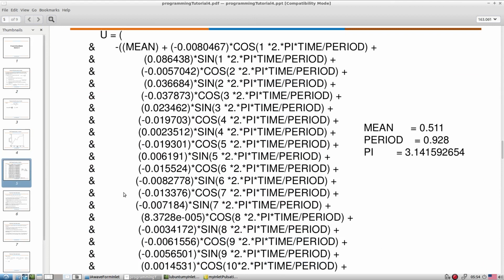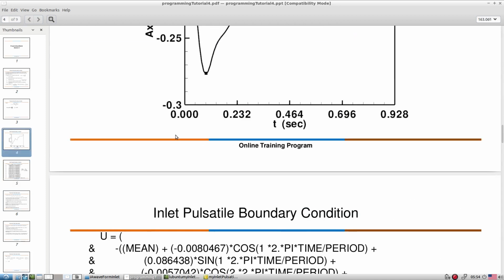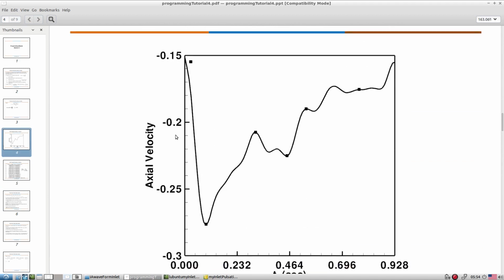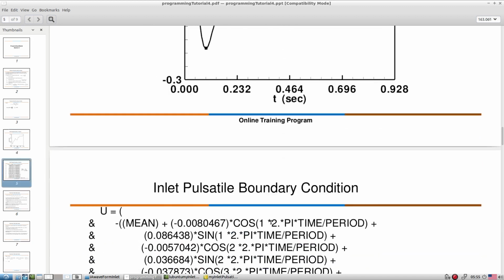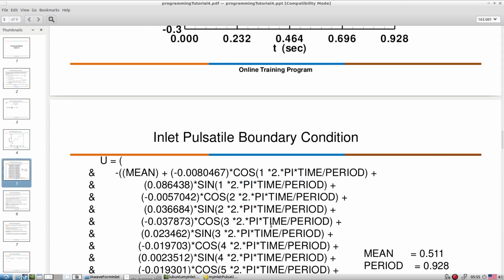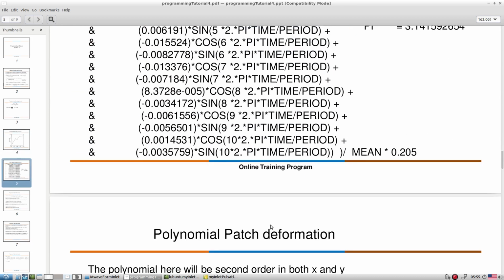So that is the idea. I suggest you also try to develop this. For application, as compared to any arbitrary geometry, you can use, let's say, flow through a pipe, but don't generate the pipe aligned with the x-axis or y-axis. First generate the pipe horizontal, then incline it to some 30 degrees or so, so your patch is not aligned with any of the coordinate system. In that scenario, that is the perfect test case to simulate this class of boundary conditions. So that is what one can do.